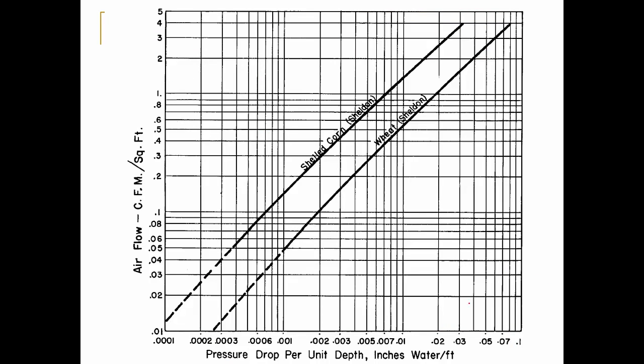So what they did is, instead of a fan equation, they typically generated these graphs experimentally. What they typically do in the lab is take barrel containers as a model bin, connect it to a fan, fill the grain to a certain level, and connect a pitot tube at multiple depths and measure the pressure drop.